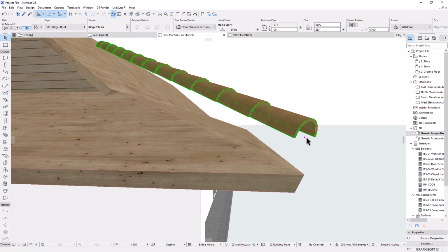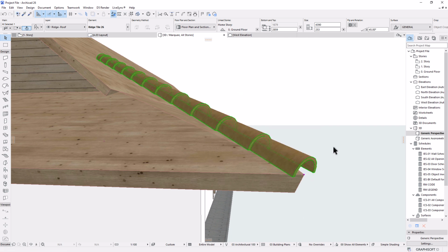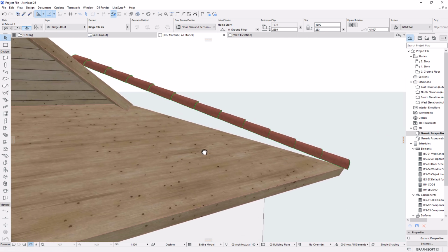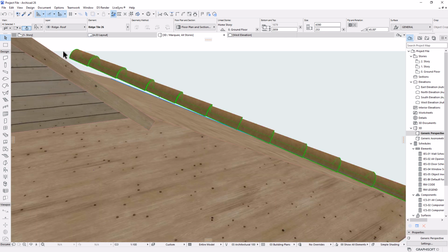Right click and then hide the layer in order to have a clear window. So I select this object and then pick this purple hotspot to activate the drag. Let's drag it right on this corner. Perfect. So you could see they're not in line, even though they are on the same pitch degree. But I would also use manual methods to place this. Once I've set one, I can mirror a copy or multiply it along the other segments, because they are on the same pitch degree.